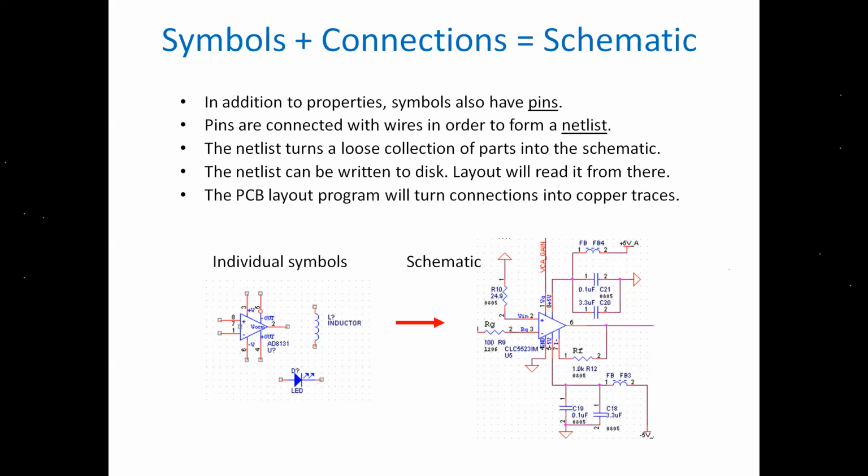This connection establishes the net information. From here, pin number 1 of the capacitor and pin number 1 of this FB4 make the same connection. This establishes the net connection, which is translated to the layout editor.